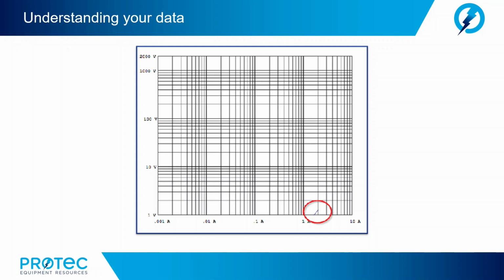Now, why is it important to know your test set and expected saturation of the CT you're testing? Well, here is an example of a test report that was turned in by a technician who was using the Vanguard EZCT test set. The technician had similar results on all of the 50 to 5 CTs that he was testing that day. Where is the knee point on this curve?